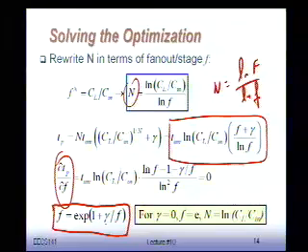However, there's one case where this thing collapses and becomes quite easy to solve. When I put gamma equal to 0, let's assume that all your load capacitance is coming from the fan-out, and we assume that the intrinsic diffusion capacitance is ignorable. Then gamma would be 0, right? If I would have no diffusion cap, gamma would be 0. If you put gamma 0 in here, you basically get f equals the exponential of 1. We know that number. It's e.